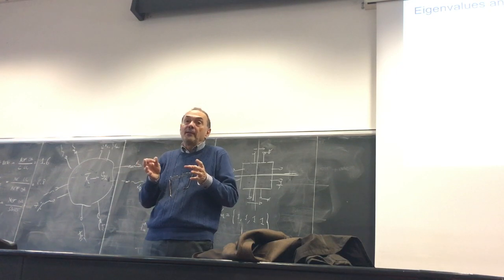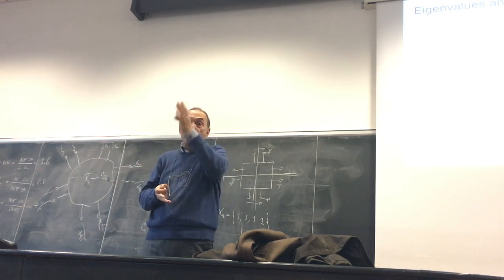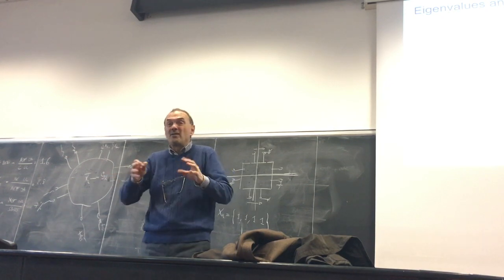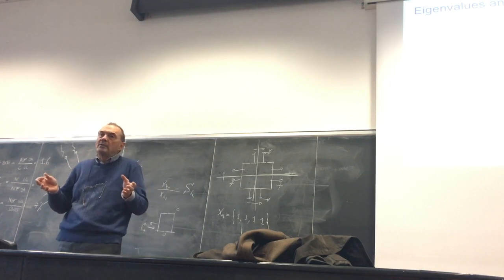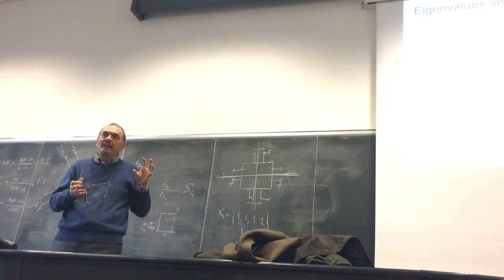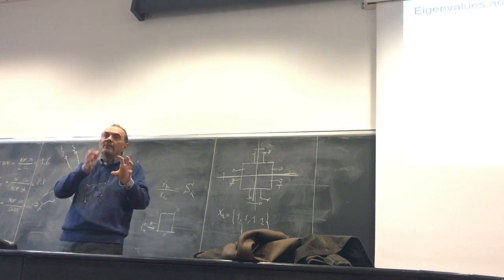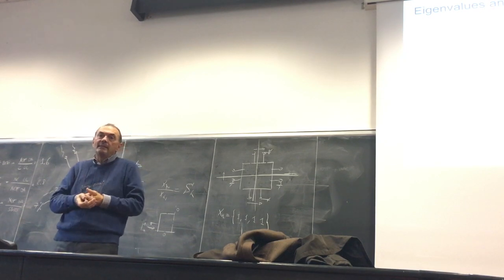But as I said before, it's relatively simple because they correspond to having placed electric or magnetic fields in correspondence of the symmetry planes. So it's not so complex. Once you have this, what we have to do is only to extract from the network the part which remains once we have inserted physically an open or short circuit along the symmetry plane.